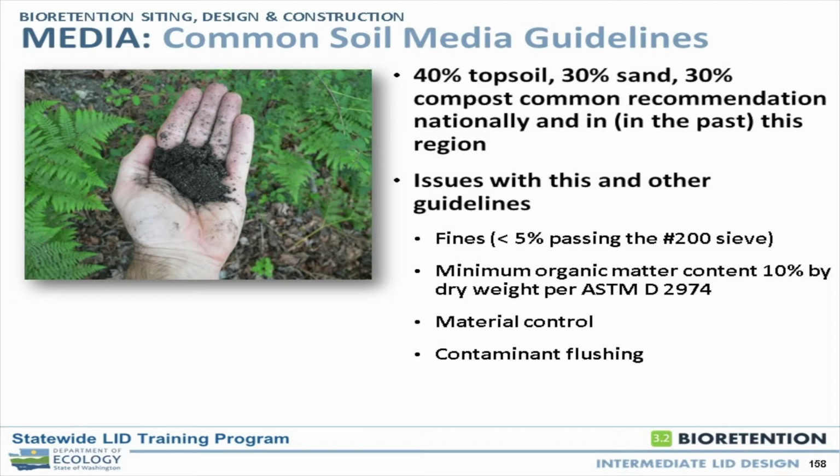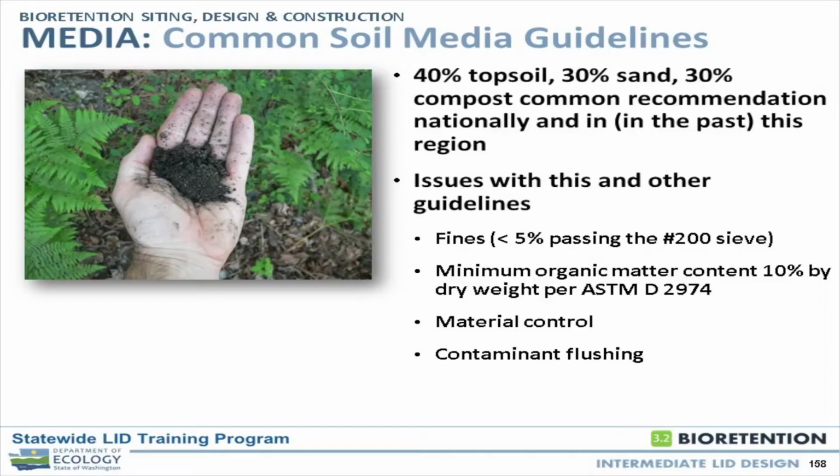Material control is huge. Topsoil, we have no rigorous guidelines for topsoil. So you could get topsoil from Bob's backyard one day and Jack's construction site the next, and unless you have a supplier that you know really well, and you're going to get sandy loam or loamy sand and consistently get that, which is rare. That's very rare. It's very challenging to have any consistency. So material control is a big one.